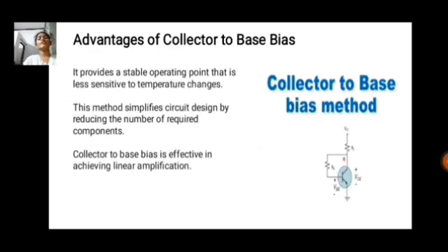In this slide, I will explain about advantages of collector to base bias. It provides a stable operating point that is less sensitive to temperature changes. This method simplifies circuit design by reducing the number of required components. Collector to base bias is effective in achieving linear amplification.